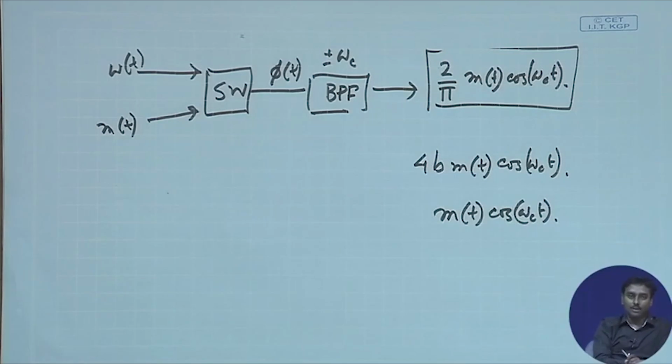Okay. So, if I do it with a switching circuit, I will be leaking power into higher harmonics. Effectively I will be losing power, and that is very important, because whatever power I put in, I want to employ that for my modulation purpose only. Those are all getting wasted.